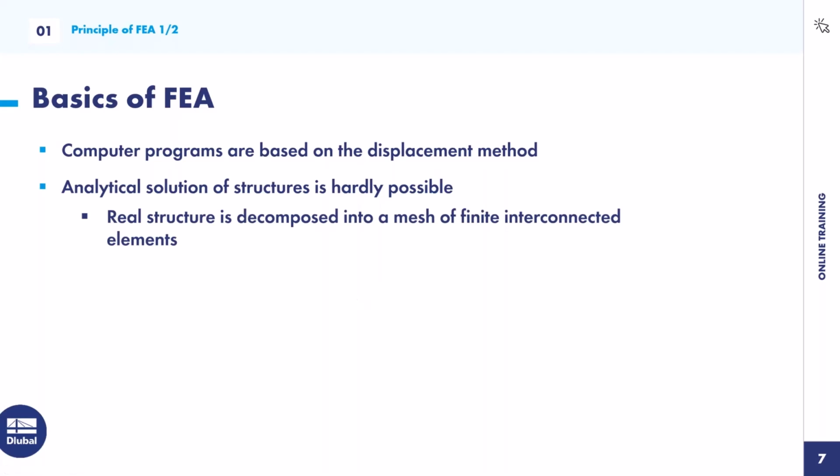So it splits up the model into several squares or triangles, and on each square or triangle it describes the continuum. This means at each border from one element to another element, you have, for example, a displacement in z direction, and it must be equal. So you have some equations which have to be satisfied.